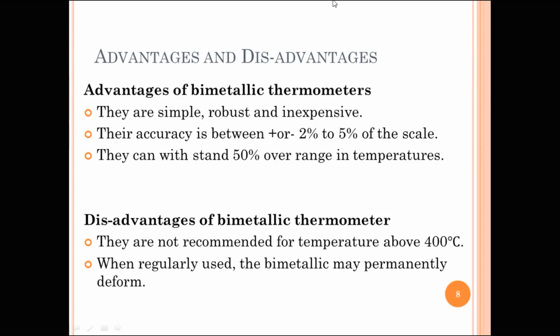Similarly, the disadvantages are: even though they are capable of working within 540 degrees Celsius, they give better performance only up to 400 degrees Celsius. They are not recommended for temperatures above 400 degrees Celsius. When regularly used, the bimetallic strip may permanently deform, which in turn will introduce errors.